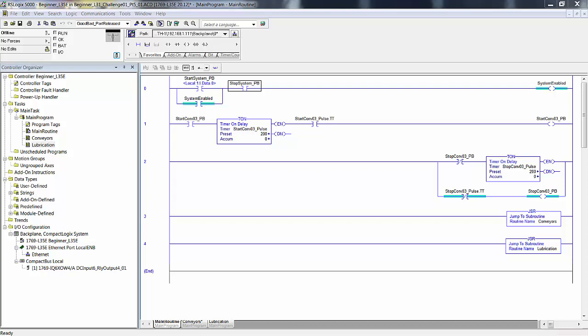The physical location of sensors is always an important criterion when writing a control program. Can't tell you how many times I was shown a diagram, I wrote the program, I got out to the field to commission the system, and the photo eyes were not where they were shown in the diagram. And that does change how you write your program. So first you see if you can adjust the photo eyes to the position that matches what you'd considered in your program. If you can't, then you have to edit your program a little bit, maybe even a lot.